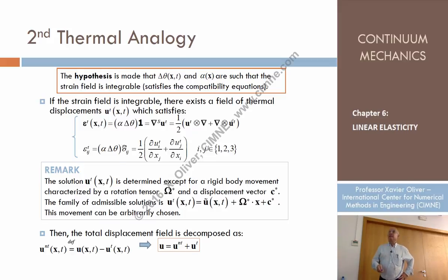If we know that, then once we have integrated that and computed the thermal displacements, we can define the non-thermal displacements as the difference of the original ones that we don't know, minus the thermal displacements that we know, because this one is known, and as a preliminary stage, we can compute these thermal displacements, okay? So we can state this equality.